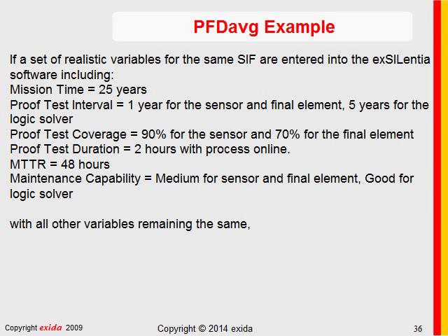48 hours, I think, is pretty realistic. But anyway, for example purposes, I chose 48. In maintenance capability, I picked medium for the sensor and final elements, and good for the logic solver because they're relatively simple and relatively foolproof.